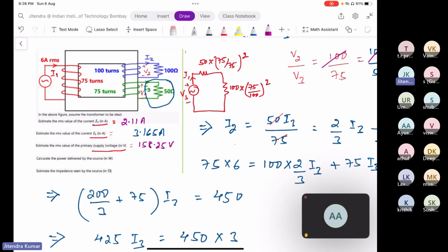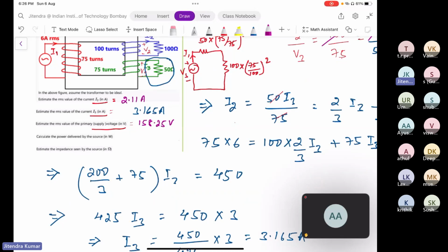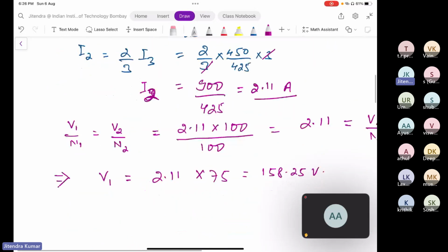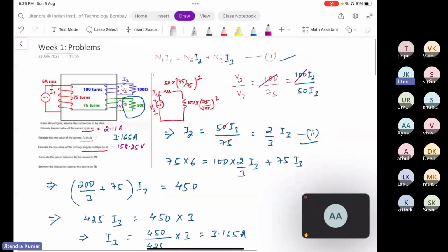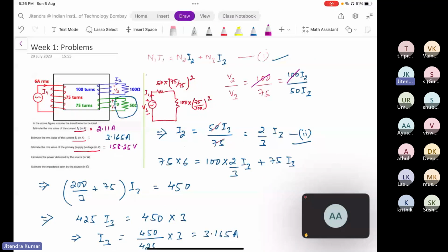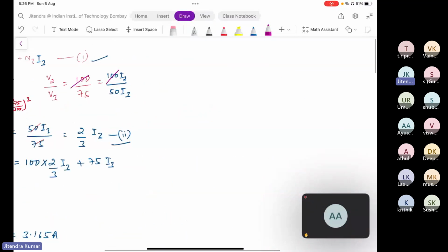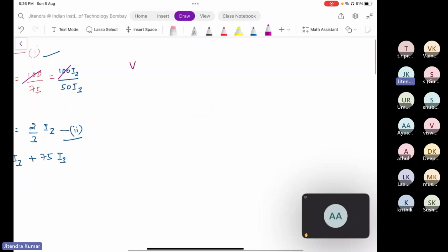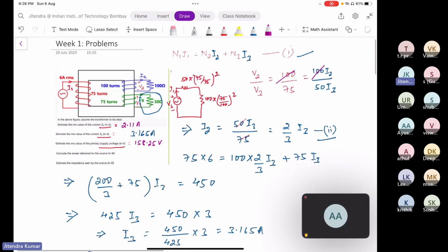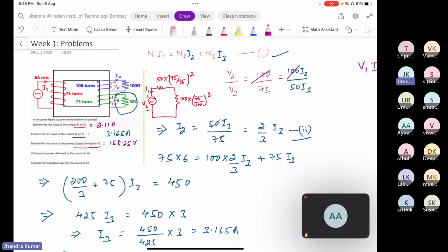So let us try to calculate both ways, and we will see if the power factor would be unity, then in that case our apparent power would be equal to real power. So V1 RMS into I1 RMS, then V1 we have found out 158.25 into 6.